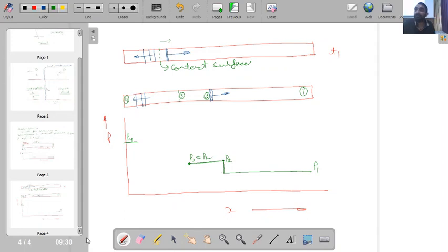Expansion waves lead to a gradual shift in the pressure, and these will gradually decrease the pressure of the driving section. So gradually from P4 to P3 pressure will decrease in the driving section because of the presence of the expansion waves. So this will be my new pressure profile over here,